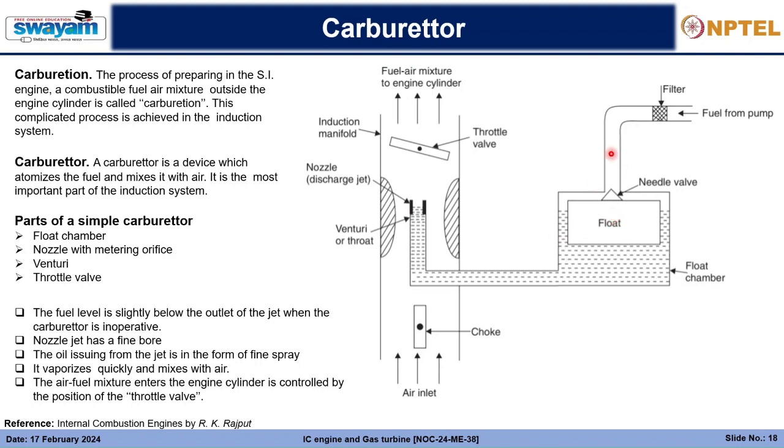When the water level decreases, the tap opens and water flows into the container. Similarly, here, when the oil level decreases as the oil is injected into the system, the fuel from the pump enters again, because the needle valve opens up. That is why the float is present, and this is the float chamber.